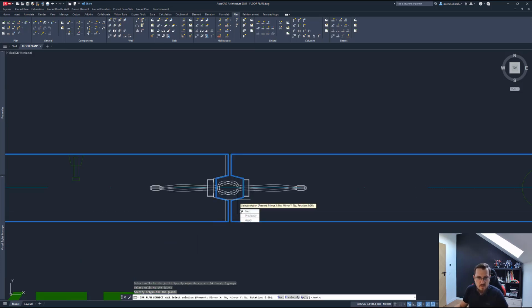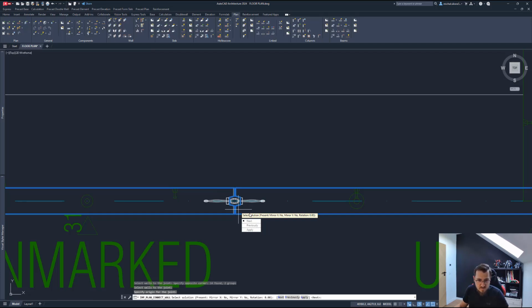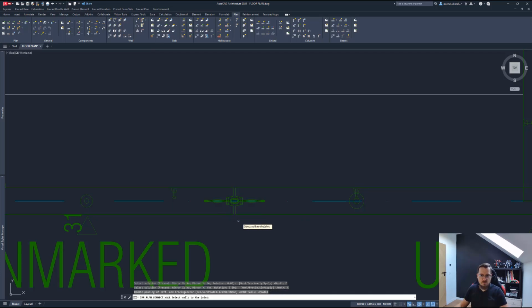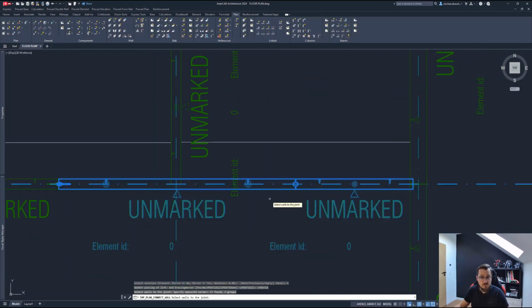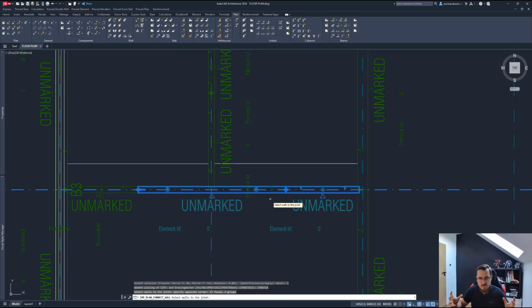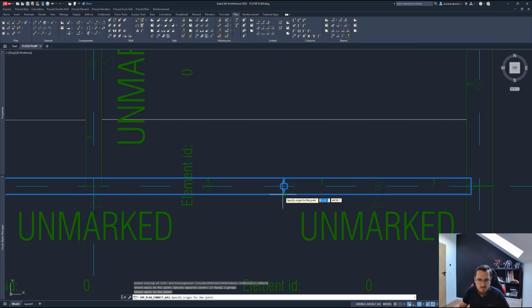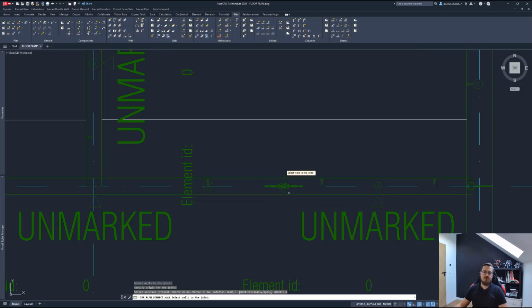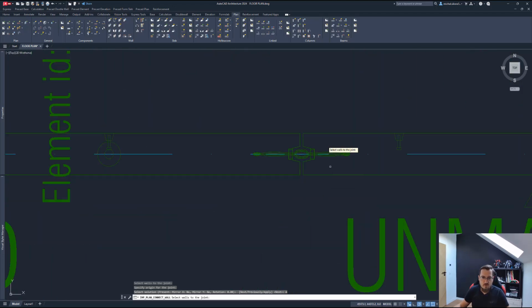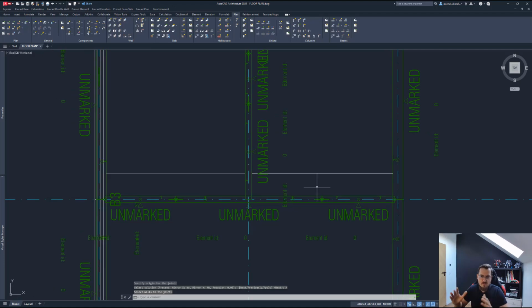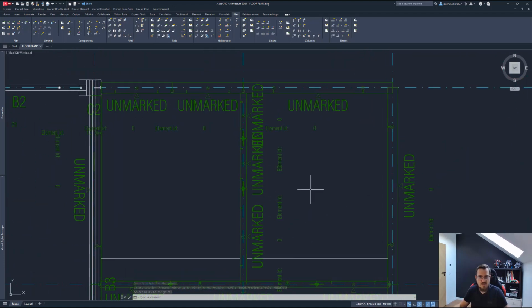Okay, and I've now applied the casting material, and I can swap the sides, or if there's a different alignment possible, it will suggest it here. There won't really be a better alignment here, so I'll just apply and update all. So this will also update the lifts and the geometry. I can also, now the command is not finished, select another collection of this type and just press space, specify your origin of the joint, and apply. And it automatically creates that connection for me, right? And let's accept that. Basically, it also adjusts the spacing between the elements if there's need for that, right?